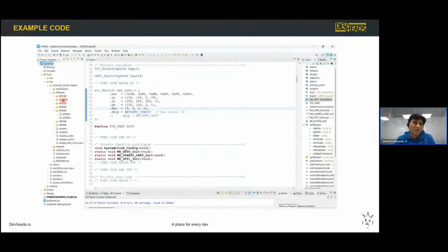That's why you can see all the other products from WIZnet show up, like the W5100 module. This is the old Arduino Ethernet shield. Then W5500, this is for the new Arduino Ethernet shield users, right? The one that we are using today for this demonstration. So this W5500 folder includes the device-specific source code. There are two source and header files. And then there's socket and wizchipconfig.c. So these are the common files. I will explain in great detail, just hold on. The point I want to make is that porting this IO library from WIZnet to any microcontroller is very simple.